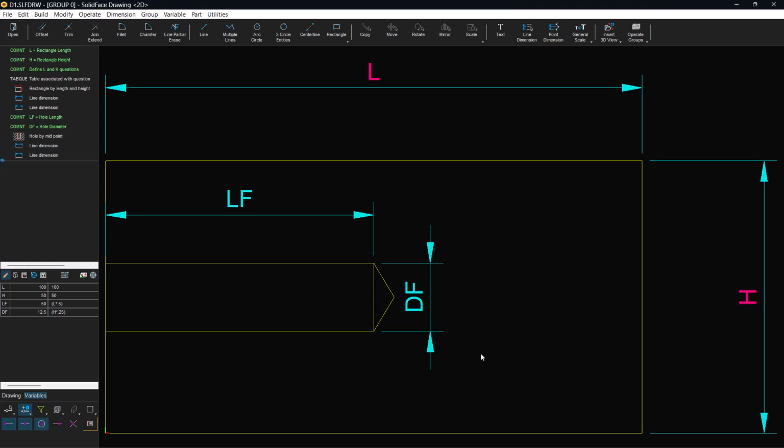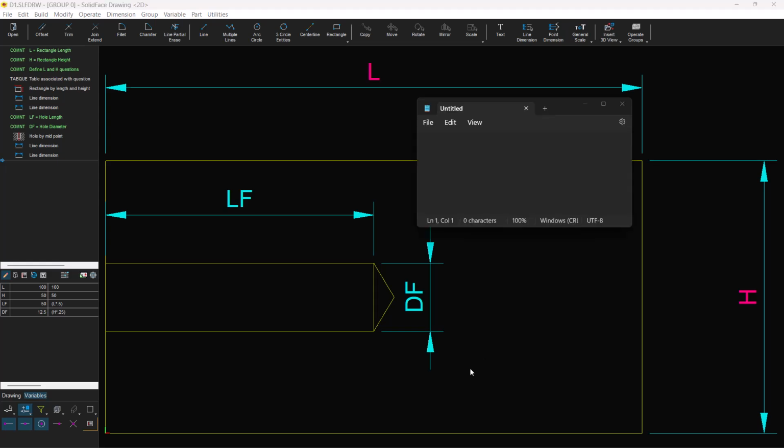The table can be a TXT file created in Notepad or a CSV table in Excel. The simplest way to create associative tables is to use tables with a question. Using Notepad, create the TABD2 TXT table. Variables and column values must be separated by a comma or semicolon. The first line of the table must contain the list of variables, in this case the variables L and H, and 3 more lines with constructive variants.